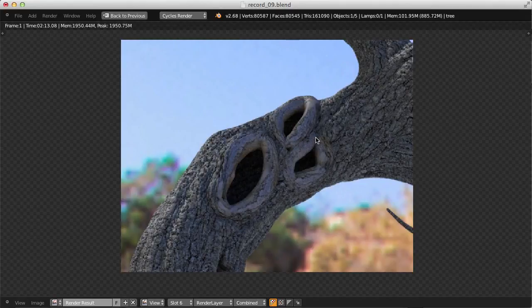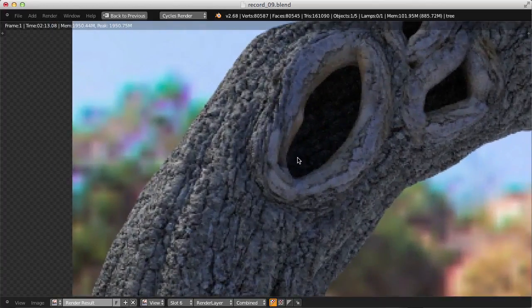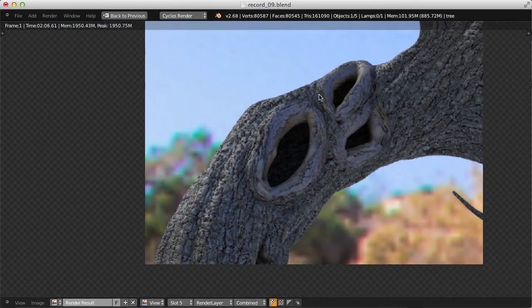Yeah, I actually think that's helping out a little bit. It's just slightly adding more definition and breaking up that specular as well, because the bump map will pick up even finer detail than our displacement map, because it's limited to the amount of subdivisions for our geometry. So keeping this bump at a small value will give us the highest frequency detail possible.